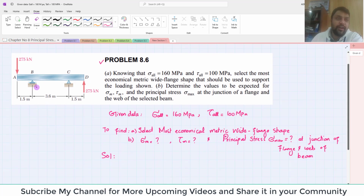First of all, you have to find the reaction forces at points B and C. For that we will remove these reactions and give the forces. Let this force be RB. Clear? And this force which is acting will act downward. Why? Because you can see this force is upward, so it will be downward, and again this force will be upward and downward in order to bring this beam into equilibrium condition.